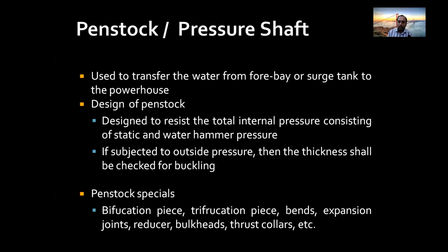If it is subjected to outside pressure, like if it is underground, and say for maintenance purposes the pressure shaft is emptied, in that case there is some external water pressure, pore water pressure, which is acting on the top. So it should not buckle under that external pressure. For that also, we have to check the thickness.